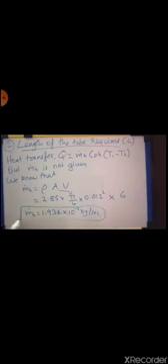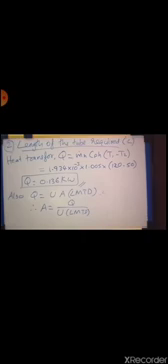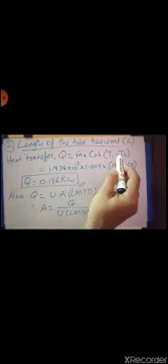We got the answer, and we have to substitute this value in the equation of Q. I am explaining it once again. Q is equal to m dot h into Cph into T1 minus T2. Substituting this, we get Q is equal to 0.136 kilowatt. Also Q is equal to UA LMTD, and the area is equal to Q divided by U into LMTD.